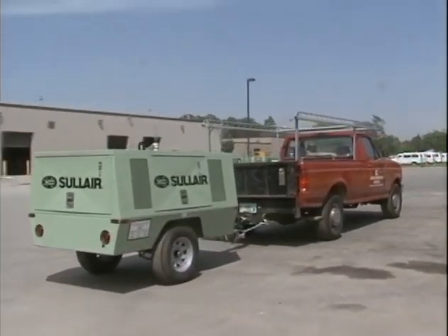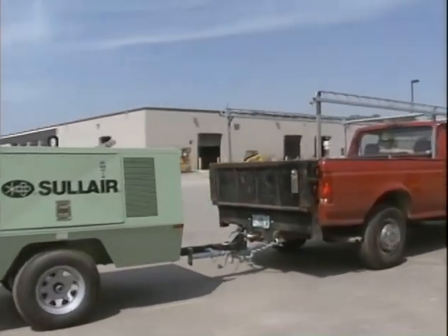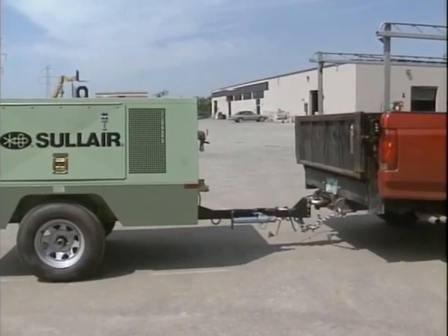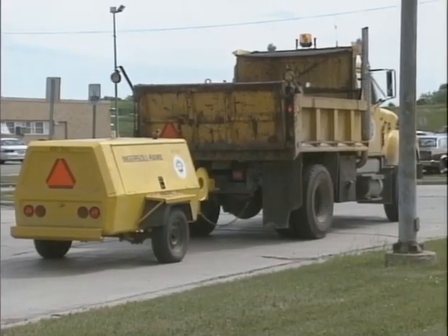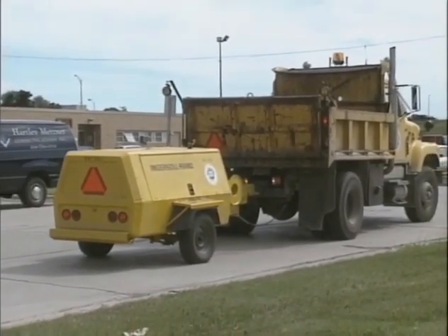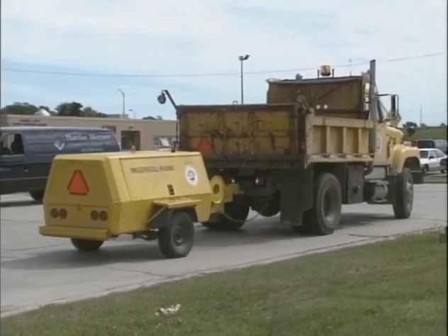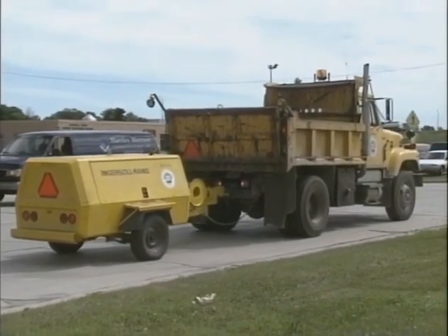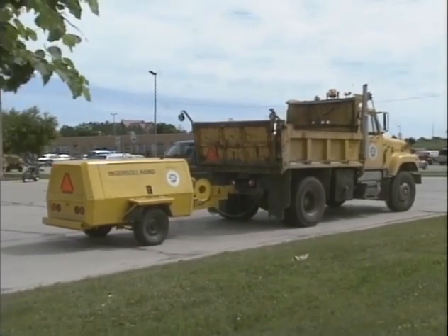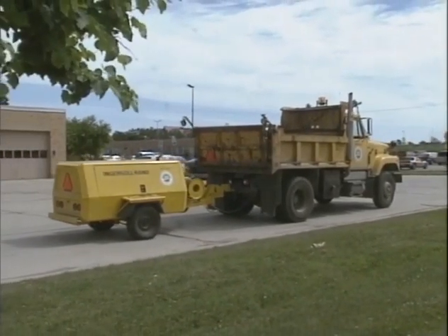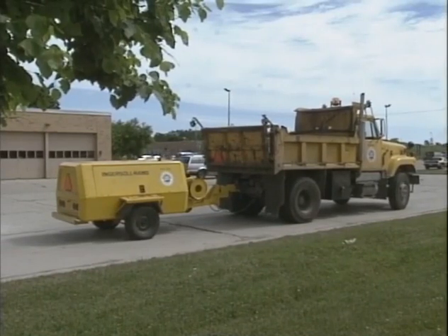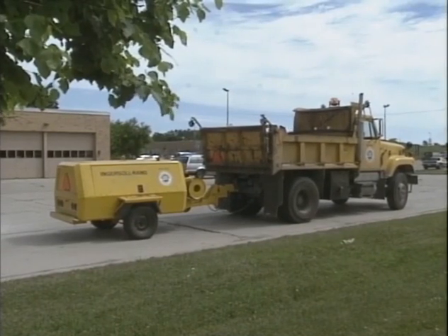Location and parking. Park or locate the air compressor on firm, level areas if possible. If not level, park or locate the air compressor across grade so the compressor does not tend to roll downhill. On four-wheel machines, park the air compressor with front wheels in straight-ahead position. Do not park or locate the air compressor on grades exceeding 15 degrees, 27%. Park so as to not interfere with traffic.